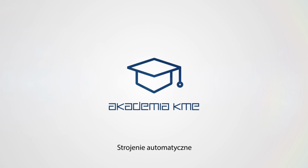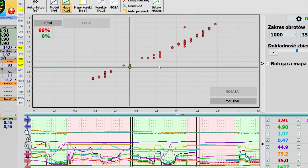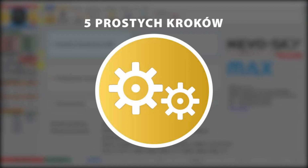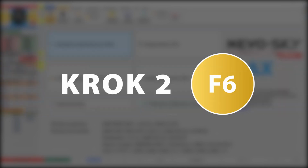In today's episode, you'll learn how to perform an automatic tuning of a KME NEVO-SKY gas system in 5 simple steps. In a nutshell, start the program, select Auto Tuning, then enter the basic parameters of your car and gas system and press the Start Auto Setup button. Perform the procedure at a standstill. Now all that remains is to perform a road test to verify the settings under load for more precise settings.